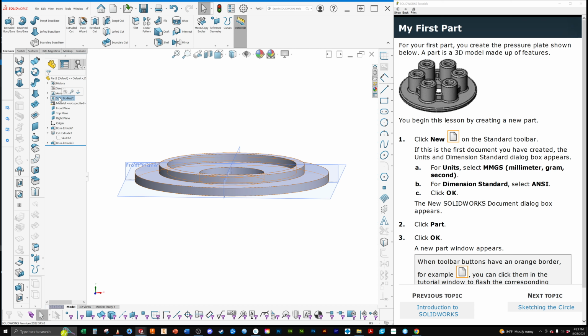Now, if I come back and I turn merge results off, what I'm saying is, hey, create a new body. And you can now see that I have two separate bodies. This is a quick way when we're doing 3D modeling not to have to create assemblies, or to be able to assign different colors to parts and do renderings. But the biggest thing is when all of a sudden you've got one giant body and you want it like 10 different parts, it was that one command.